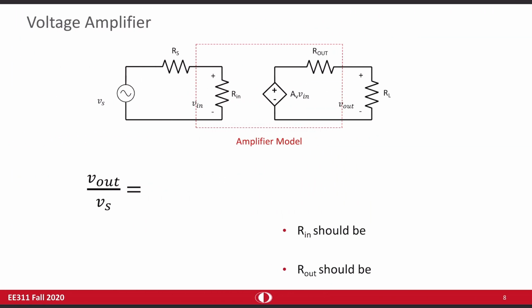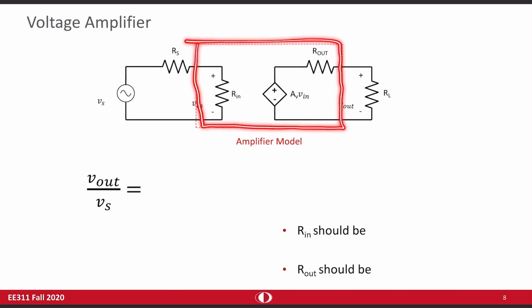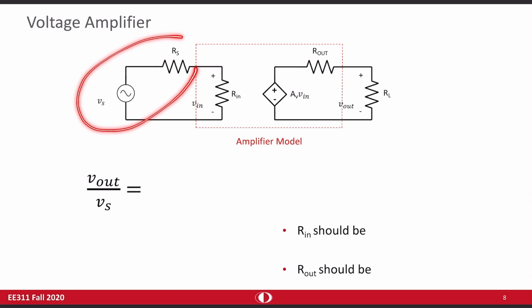amplifier, the same story. We have control in this box. And even if you use many complicated transistors and circuits inside, eventually this amplifier can be modeled by these three components: gain, output resistance, and input resistance. And source is at the control of the customer. Load is at the control of the customer, so you cannot control RL and RS.